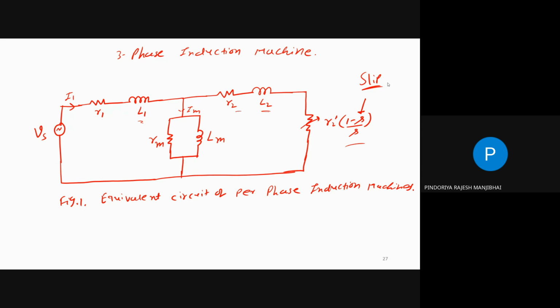So we can say an induction machine never operates at the synchronous speed, correct? So that's why in the induction machine slip will be generated, but in the synchronous machine slip will not be generated. So there is a major difference, and many industries ask this type of question in interviews, correct? So why does a synchronous motor not generate slip, but an induction motor does?